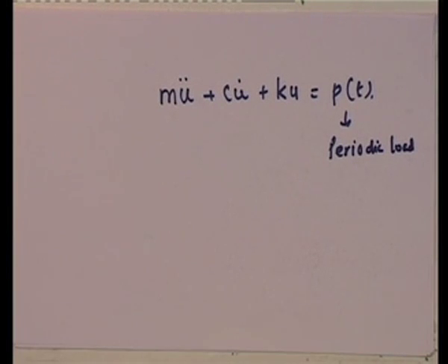If this is the periodic load and I want to find the response for it, note that I only need to find the particular solution, a steady state solution, because this load lasted forever. You do not even know what the initial boundary conditions were. The transient is gone. So we will look at the solution.